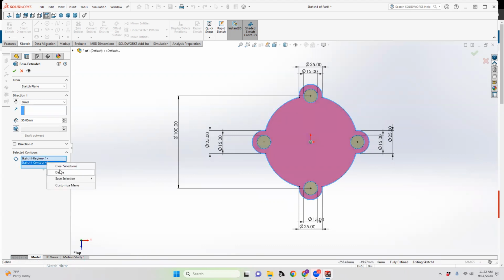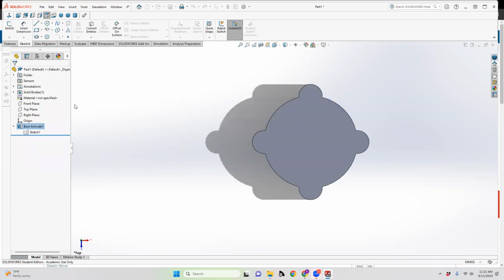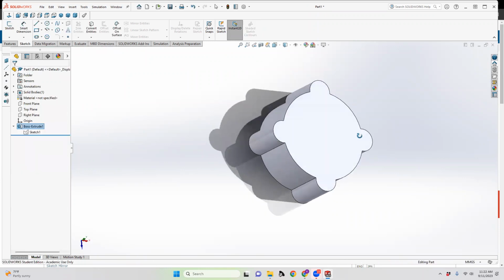So you want to avoid contours for now because reasons. We'll explain more about that later. Trust me, I'm a doctor. So we can select region 1, which is everything here in purple. And if we select one of these regions, we can individually select these areas and they'll change colors. Then when we go to do the extrusion, everything is the way that we had it originally.